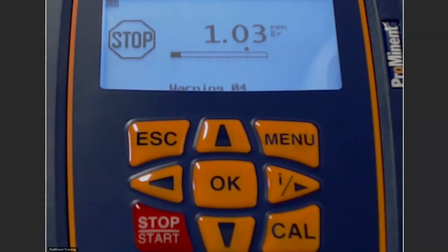So one of the things we are challenged with is to match the DPD type test. That's the same test that our DT colorimetric test kit does for us. When we take that 10 milliliter sample, one of the things we add is a buffer.